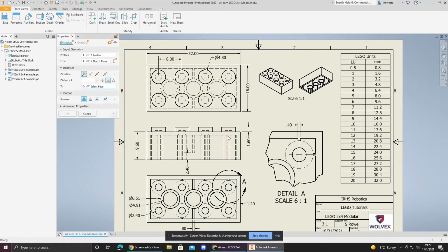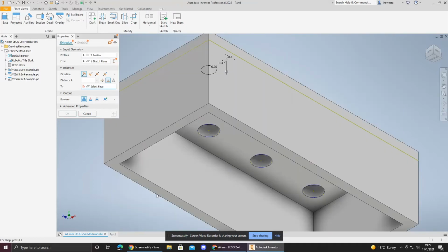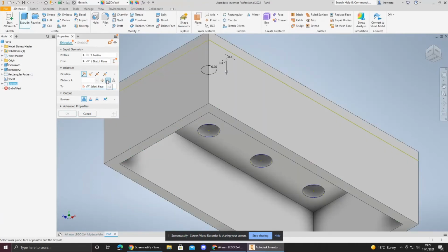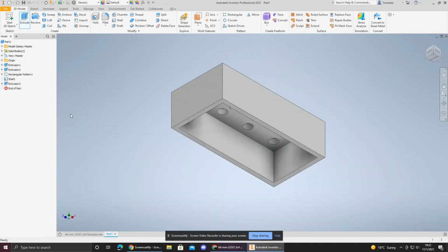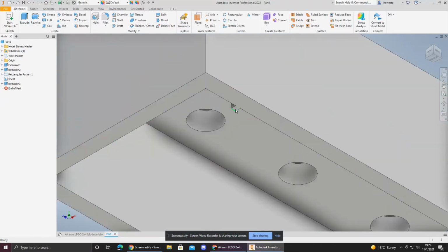These are the small extrusions in here. We can see that they reach all the way down, so you can simply hit the 2 distance and then select the face which you would like it to go to, in this case the bottom. It will make it perfectly flush. We can now press OK, and the extrusion is complete.